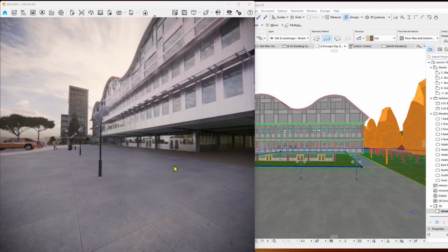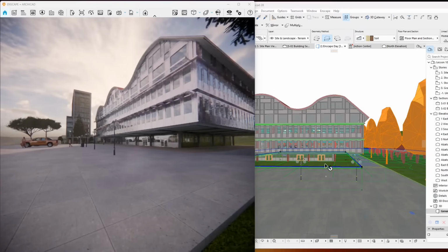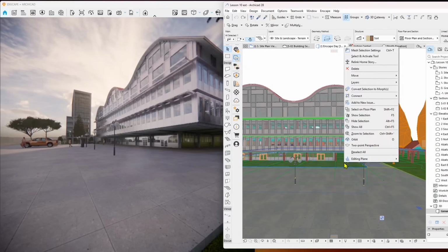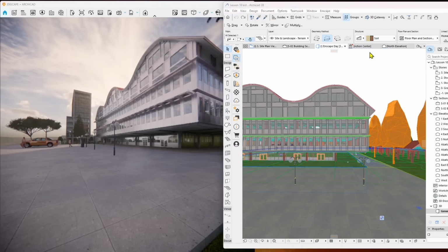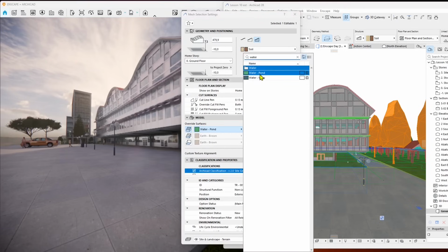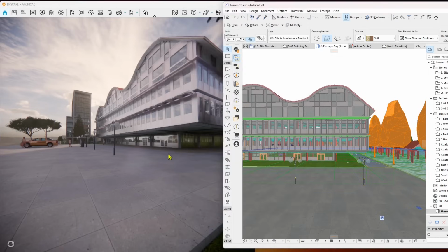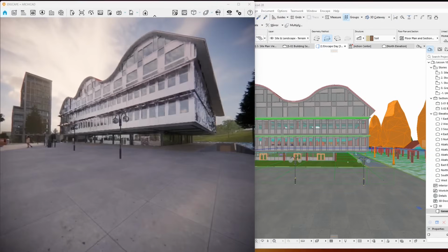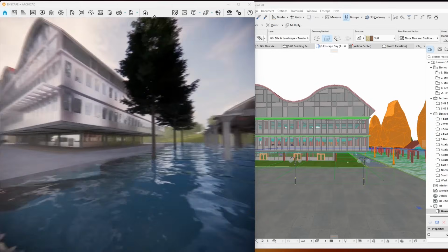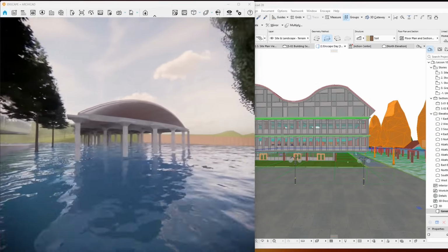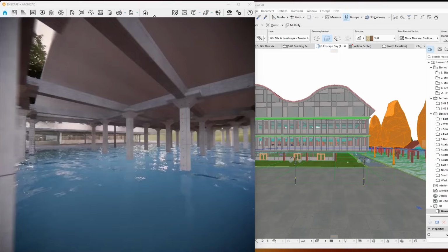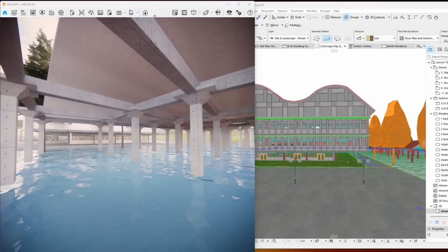So be careful with the overlapping geometry also with using these materials, but in general, any material in Archicad and Enscape. So let me apply water here instead of grass. So I'm going to type water and apply water pond this time so we can see another one. And look there, so I applied the water all around the scene here, even in the trees and even in this architecture, but that's again to just check the water material. You can see it looks really beautiful and animated also.